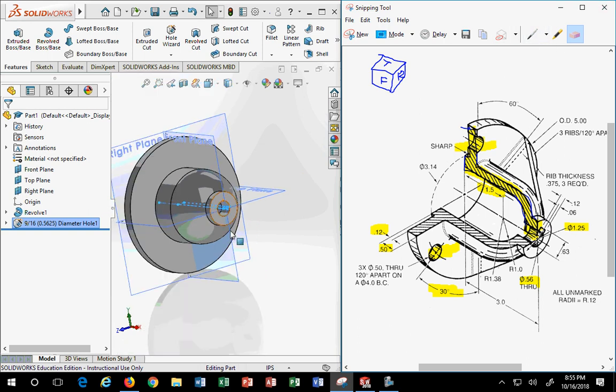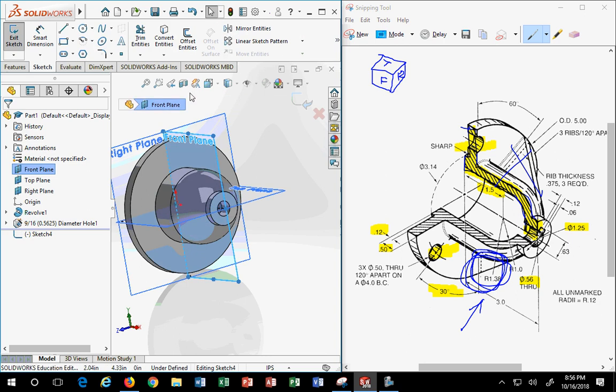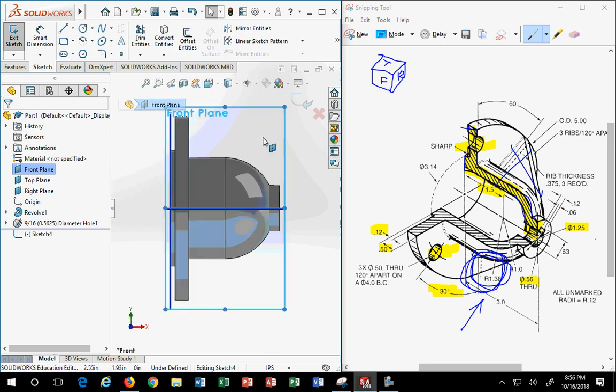So when I'm over here, I'm trying to think, how am I going to build this? Well, back to your teacher and her lazy habits. There is a rib down here. I'm not going to try to draw this rib over here, or the one that I can't see out here, because they're not in a normal plane position. I would intentionally pick the object that is at least lined up with a standard plane. That's the rib I would want to focus in on, so that when I go to the front plane and create my new sketch, that would be the place I want to be.